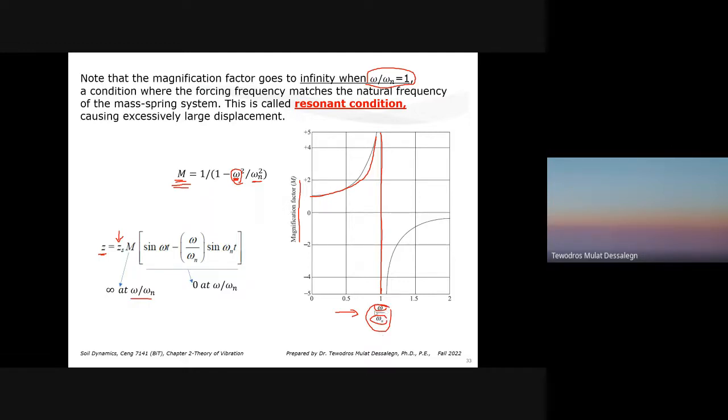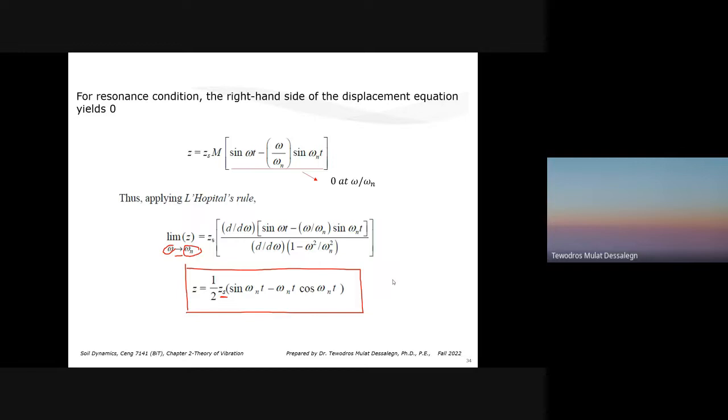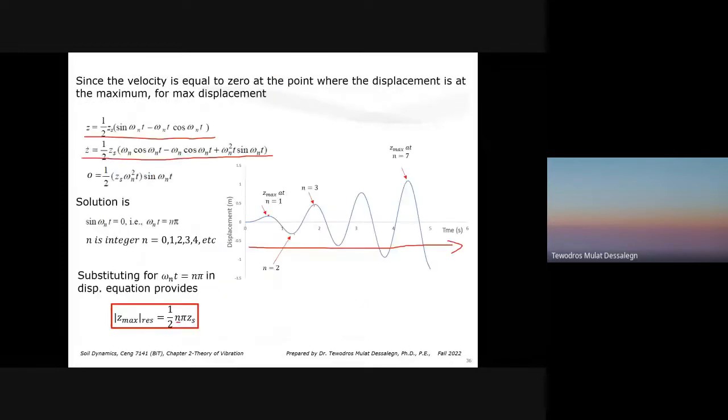It can be an earthquake or a machine vibration, but wn is the system frequency, the natural frequency of the soil with the foundation, so we can calculate this. We have seen how, in resonance, the amplitude progressively increases with time, and at some point it results in failure.